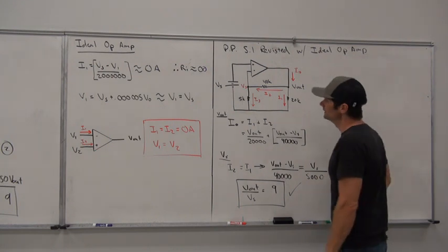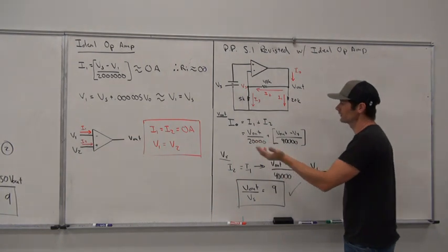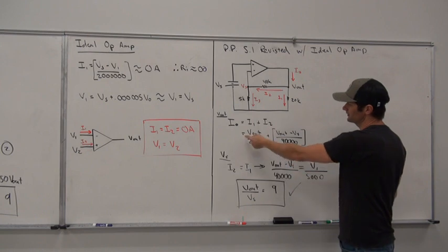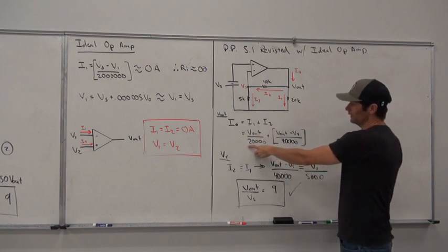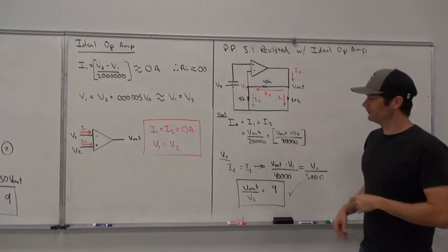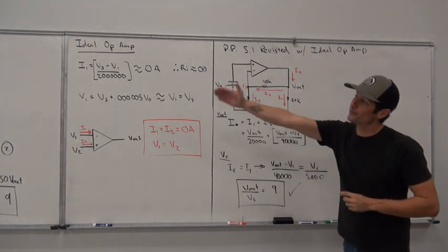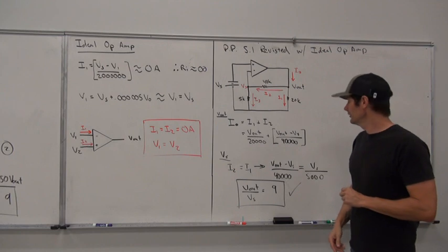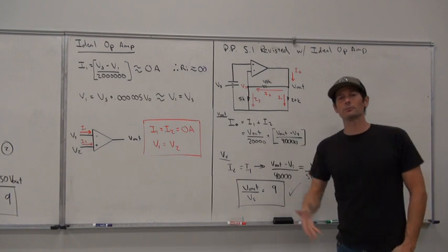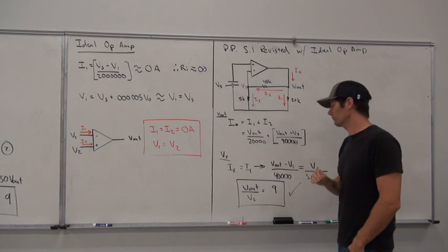Just quick KCL. If we wanted to find out what that current would be based off whatever value of Vs, then we would say I0 is equal to I1 plus I2, which is equal to V out over 20,000 plus V out minus Vs over 40,000. But how would we know what V out is if we don't know that gain? So let's prove really quick that what we found through nodal analysis on the left over here, we could easily find that gain very quickly, with whatever Vs is going to be multiplied by that gain on the output. We could find that current very simplistically.